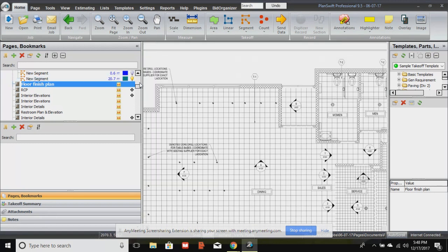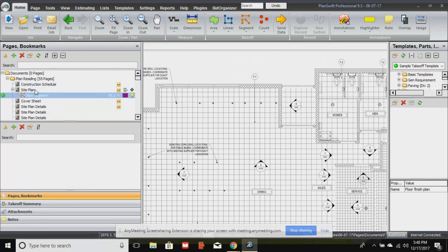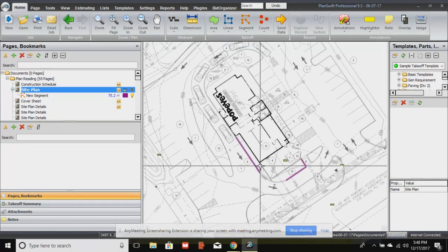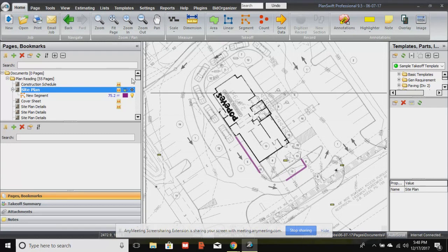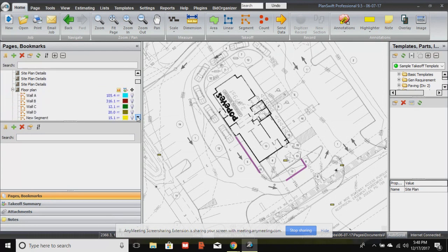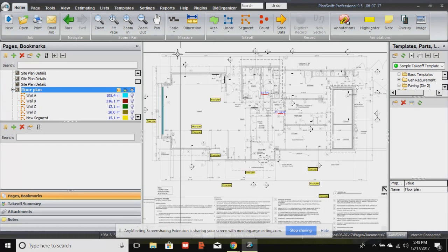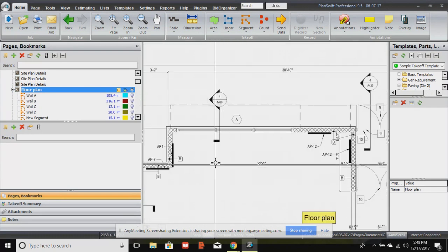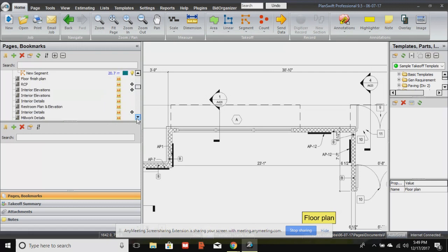All right, so to recap, 4 views. Most basic is our plan view. View of the project as if you're hovering over it, aerial view, not much detail, but gives you a good idea about your project. Then we went to our floor plan, because the floor plan took us to a lot of the other views. From our floor plan, we went to section view: a view of the project just at that one point in time, as if we've cut it from top to bottom like a knife, and now we're going to see our interior construction, heights of walls, and so on.